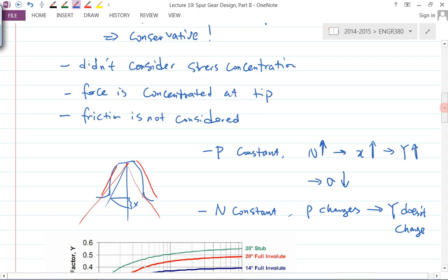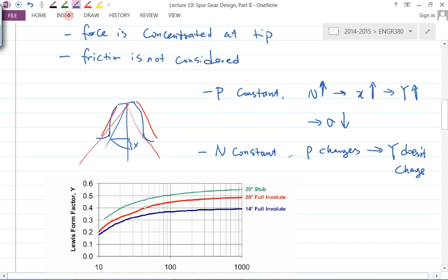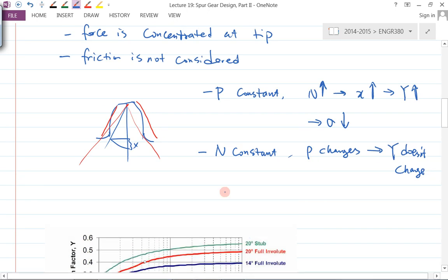Actually, it's quite easy to understand. If you remember, we have two parameters. One is called addendum, the other is called what? Dedendum, right? And the addendum value is, what was it? I think it's 1 over P, and this is 1.5 over P, something like that. So if I'm correct, if the P doesn't change, then actually the addendum and dedendum don't change, right? They don't change.